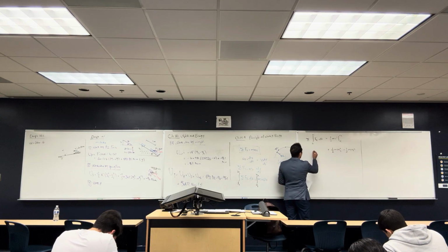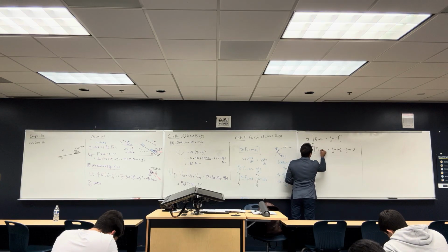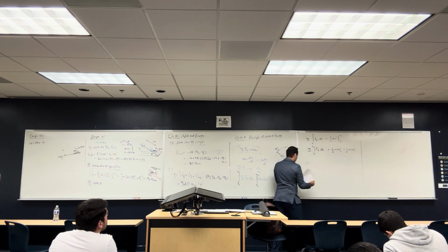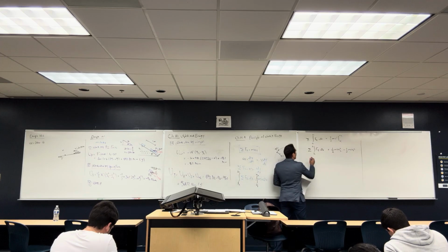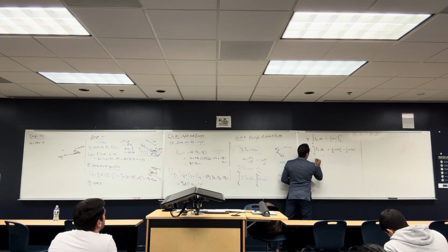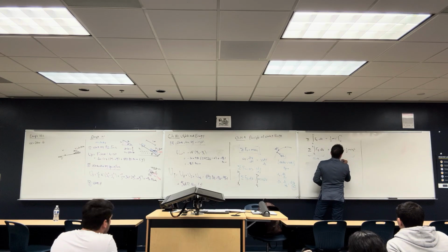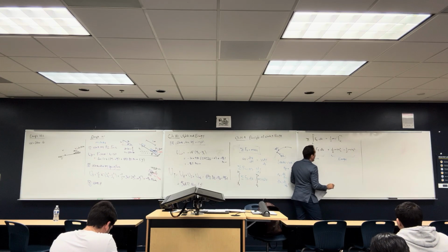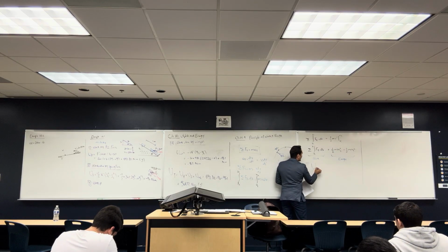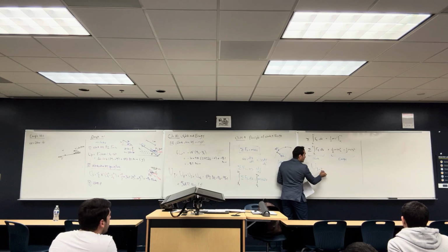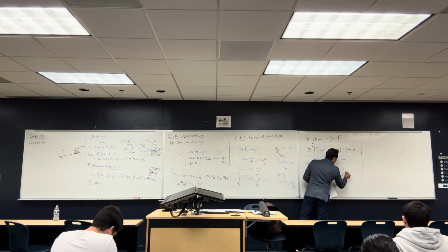So what I did right now: from s1 to s2, when you multiply force by distance, that is the general equation of work. That is work, and that is energy. We can say this is the work done from point 1 to get to point 2, and this is your kinetic energy at point 2 minus your kinetic energy at point 1.